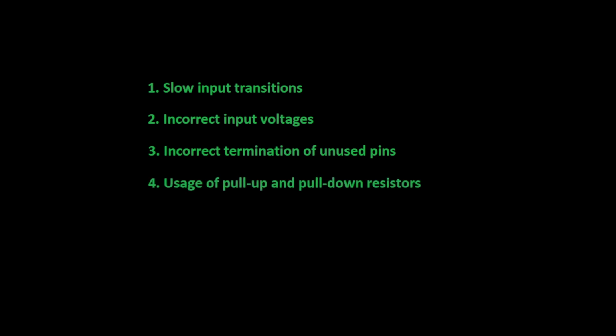It's not uncommon to see pull-up and pull-down resistors used incorrectly or sized incorrectly for a particular circuit. And last but not least, it's common to see a lack of ESD protection. Although most logic gates have some built-in ESD protection, it's really not intended for system-level applications, and we'll talk about that a little bit more.